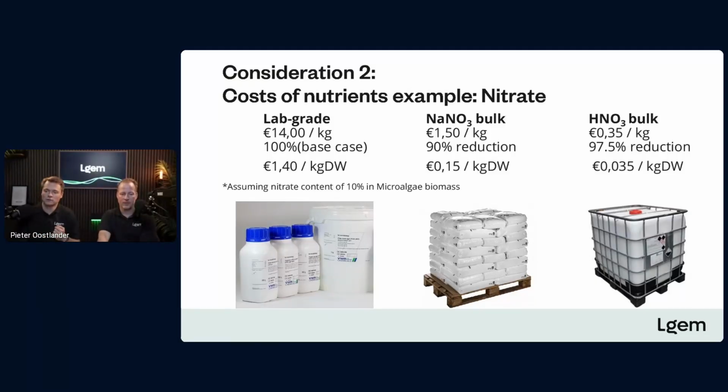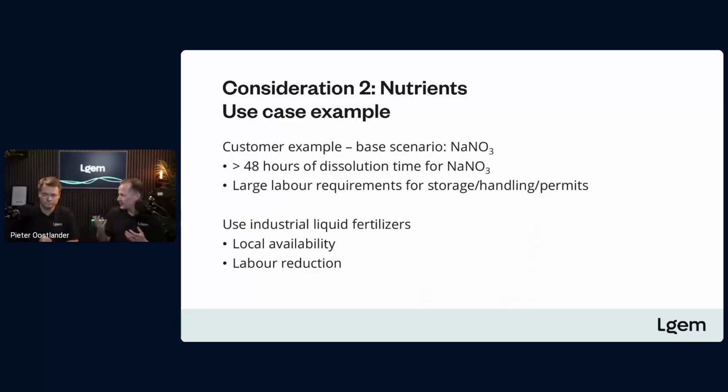Yes, and we have some to add to that. We have some experiences on this specific topic where operators become impatient. They dose huge volumes of sodium nitrate or potassium nitrate, and they throw it in an IBC or the tank where it is mixed. At the end, everything sediments in the bottom. The tank clogs up. The pump, the lines around the pump used for mixing can clog up and even potentially break the pump. It's difficult to control. It's an operational risk, and we should avoid this.